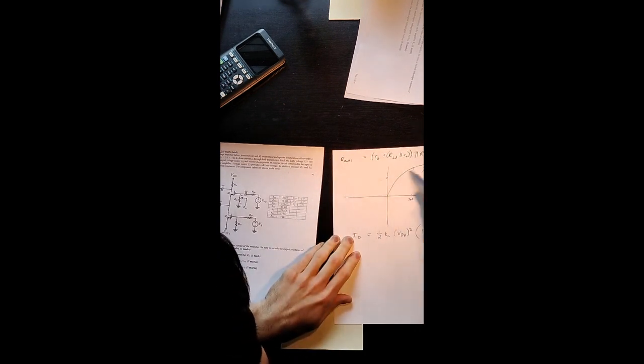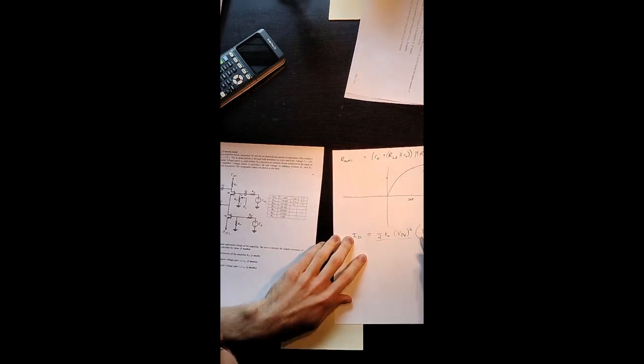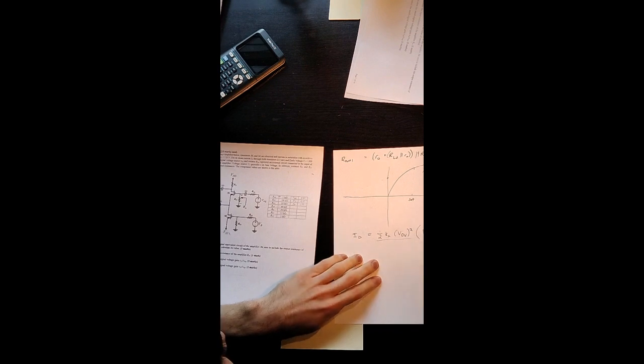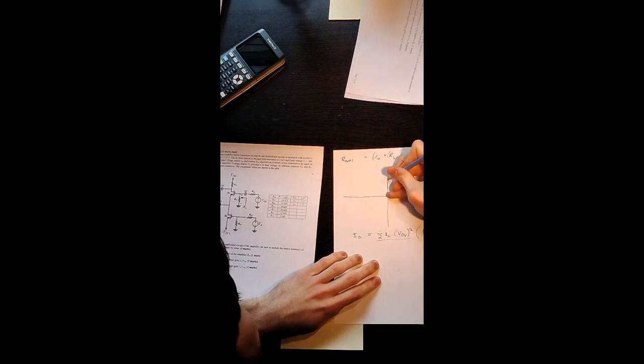So we would be outside the saturation when VDS is equal to 0. However, we know that the value of ID, hypothetically, at this point, along this line, would be just 1/2 Kn VOV squared, because this term would go to 0, so you'd be left with 1 here. So the height here is equal to ID through the current source only.